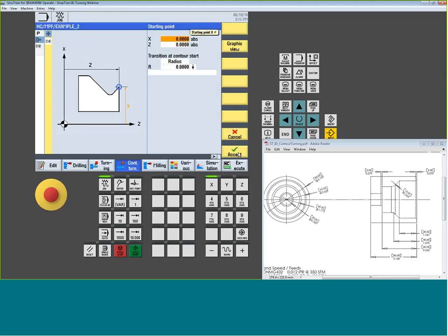So the difference here really is we're using an OD starting from a small diameter working to a big. Now we're going to start from a large diameter and work down. In this case, I said that I wasn't worried about facing it, but I do want to get this chamfer of 0.079 in. So I'm going to start at the bore diameter, which is 2.559. I'm going to tell the system that I have a chamfer leading into it of 0.079. Now you see this little picture?